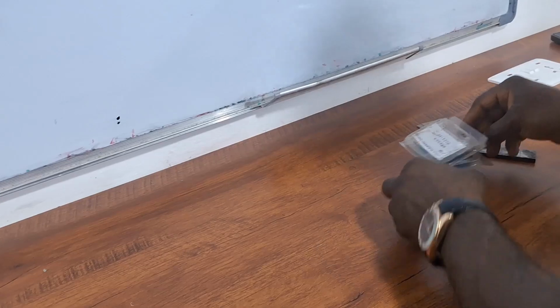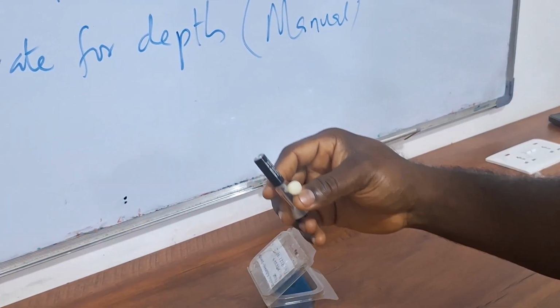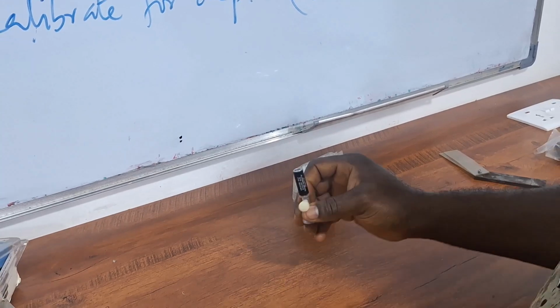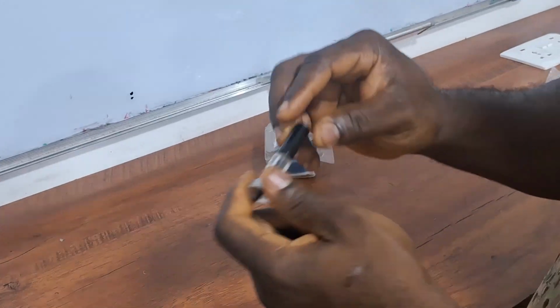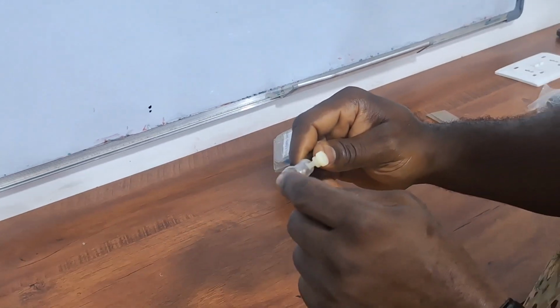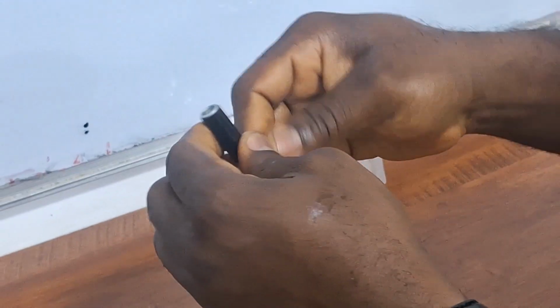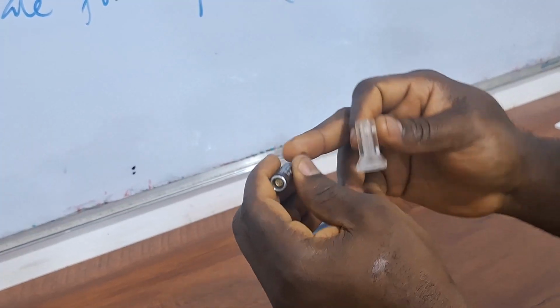The next one we'll be looking at is the bolt hole probe. This unit does not have the capability to perform bolt hole inspection, but this is a bolt hole probe. This is the manual type, so it does not require you to connect to any rotary unit; you manually rotate it. Per the design, you will see this is detachable. This is the probe itself, which is more like a pencil probe.